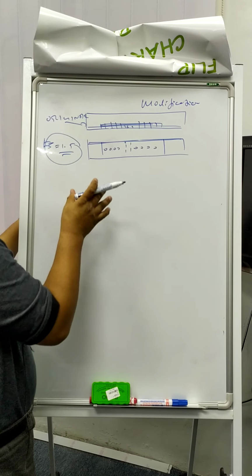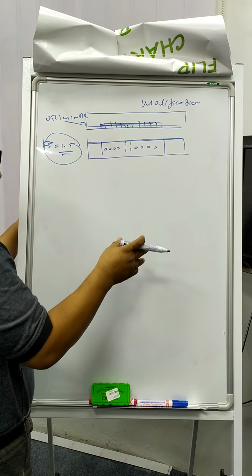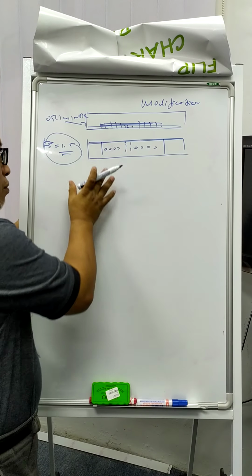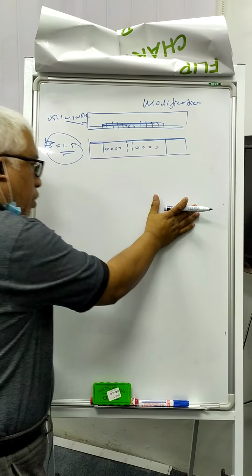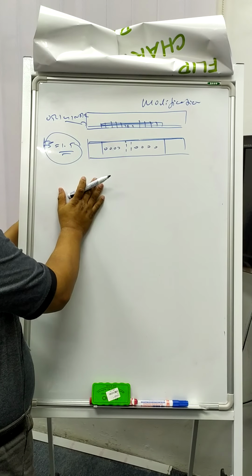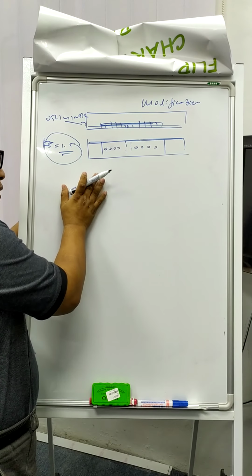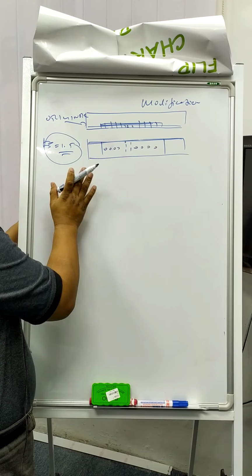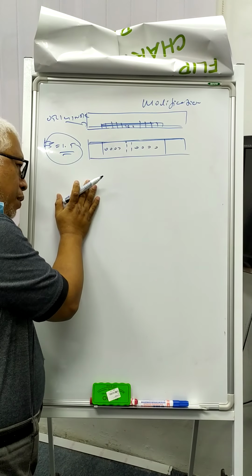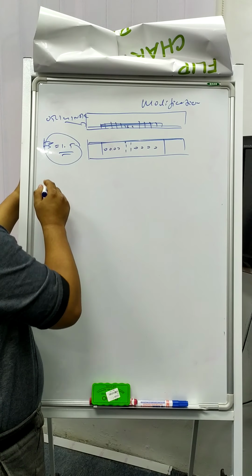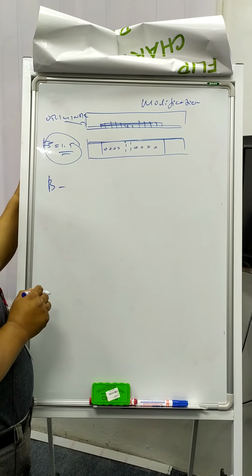Before you do the detailed stress analysis, you have to go through the design requirement, Part 25. For Airbus it is CS Part 25, and for the FAA it is FAR Part 25. The content is almost the same, so I just put in the general content. First you must look at subpart B.